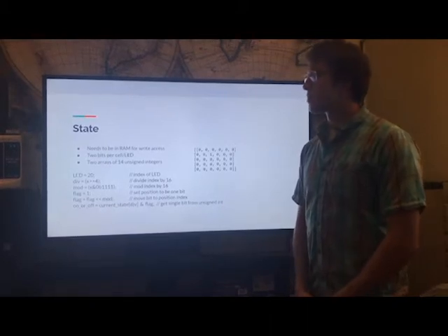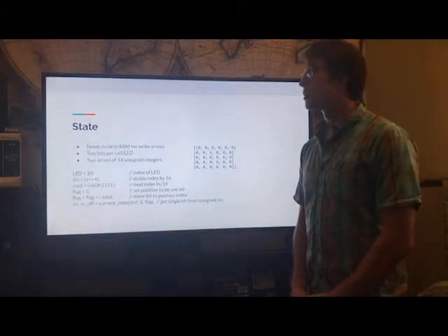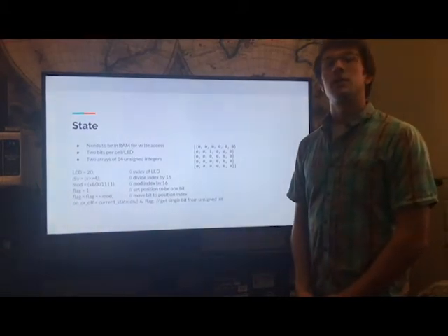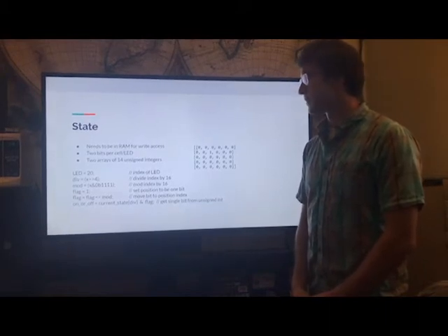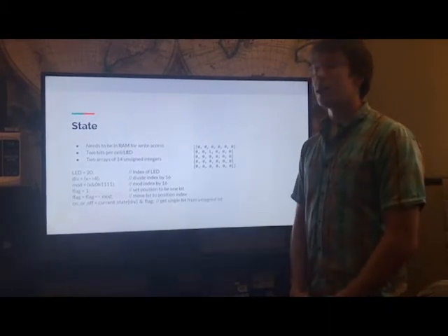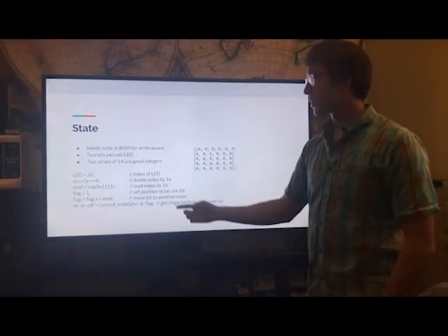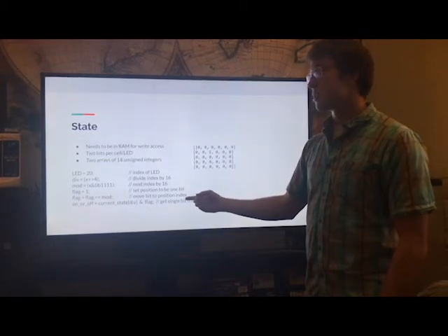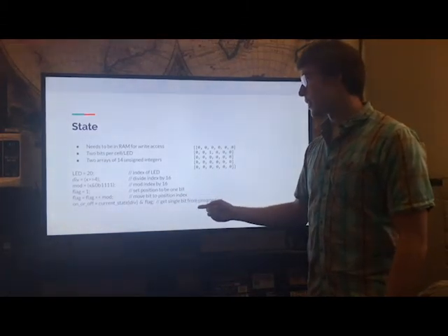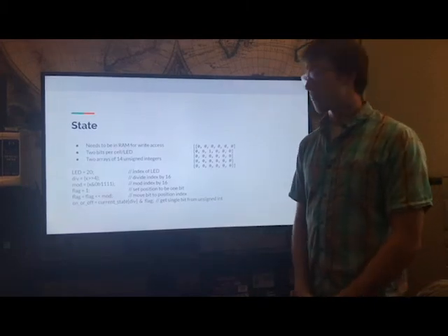We also performed the division using bit shifting and the modular arithmetic using logical AND because it was much more efficient for the processor. This is the code that we would use to actually access or set a particular bit in the field, where we divide by 16, perform modular arithmetic, move a specific bit to that location in the array, and then perform an AND to get the value of that single bit.